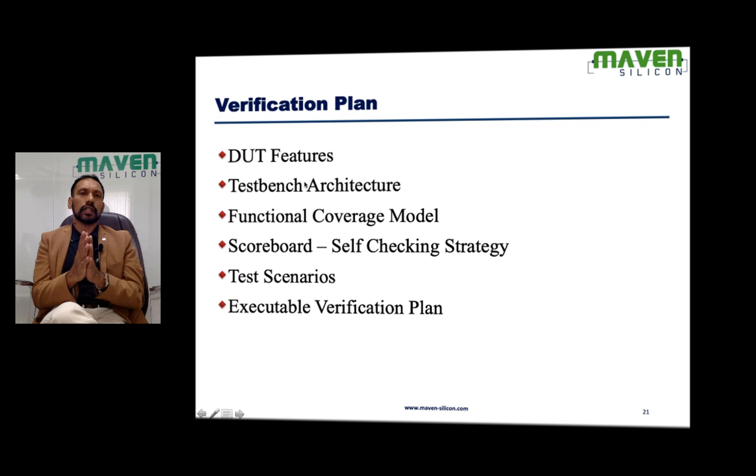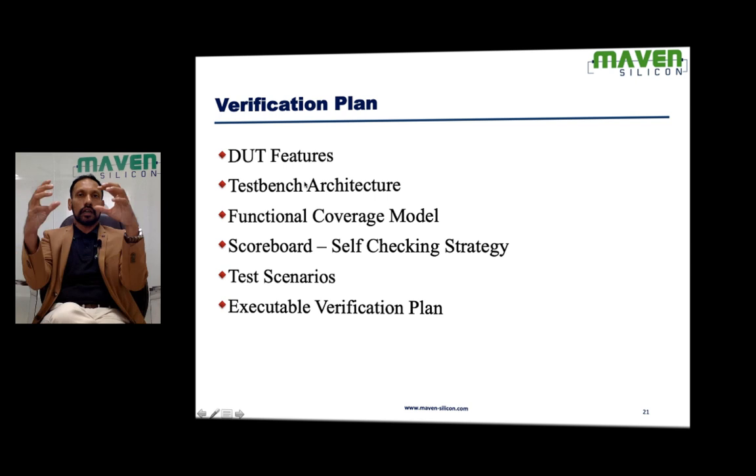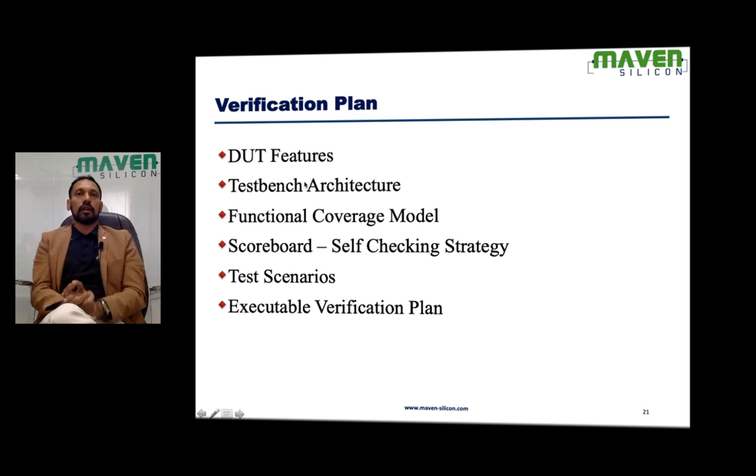So basically, the test bench architecture will have all the details of the test bench, like how many generators, how many drivers, how many monitors, what kind of scoreboards, from where we are going to collect the data, and how we are going to compare all the packets. And then how are we going to connect the coverage model with the scoreboard? Are we going to use mailbox, or are we going to use callbacks? That's what the architecture is going to define.